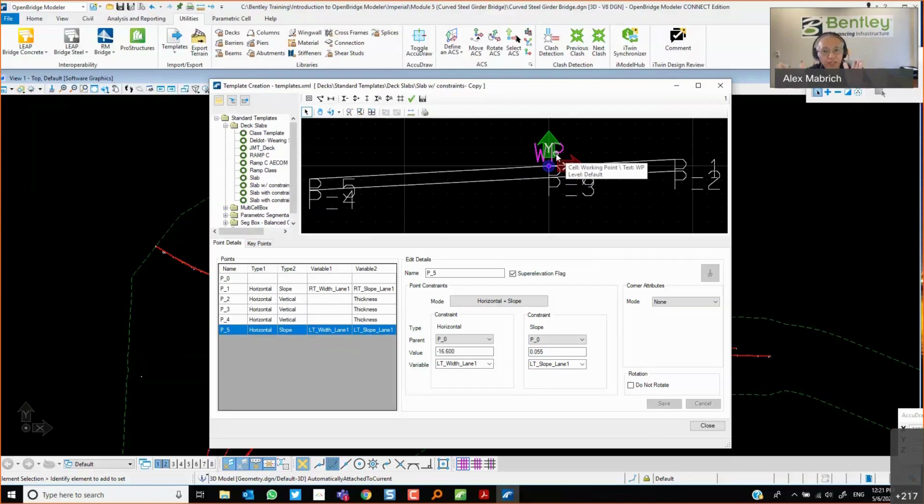I don't need to offset the deck or anything like that. We got those commands, but in this case, no need. It's just playing with the dimensions of the left and the right, right? So that will do it, right? Now, remember, I'm applying directly the super elevation here, right?